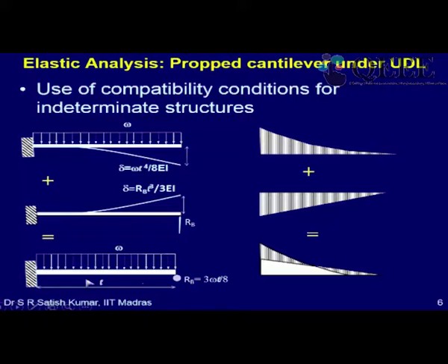So it will become a regular cantilever, fixed end and a free end, subjected to UDL, and that is what is shown here. And under this W, we know that you can use the previous Euler-Bernoulli equations to solve this, and you will get the tip deflection as WL raised to 4 by 8 EI, where EI is the flexural rigidity of the beam.